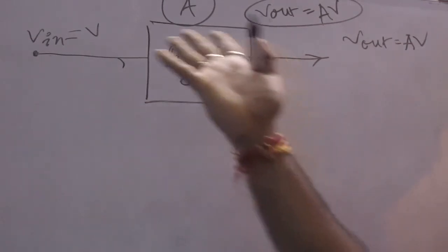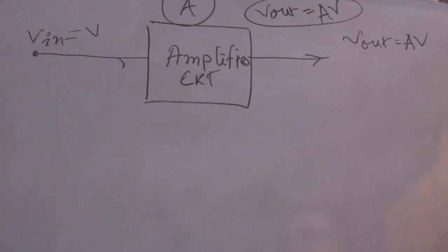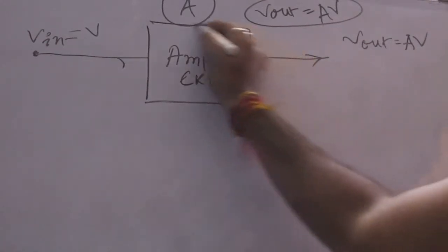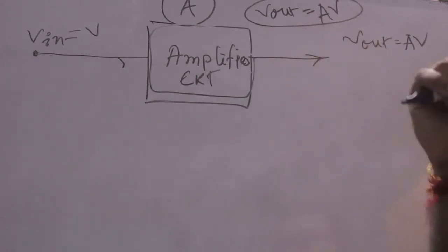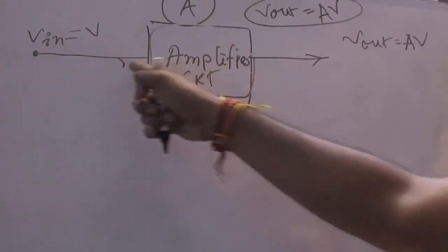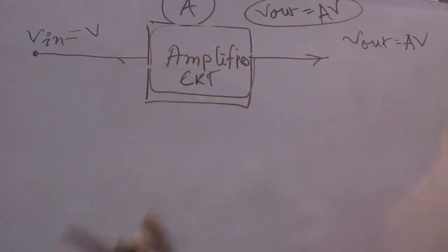So we can say that after prolonged time in the simplified amplifier circuit, the continuation of this process results in heating of the circuit, which results in energy loss in the system. And due to this energy loss, the output goes on decreasing, so we will not get any sustained oscillation. So we have to modify this circuit by the implementation of some new element.